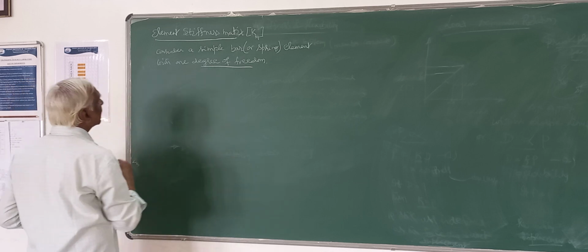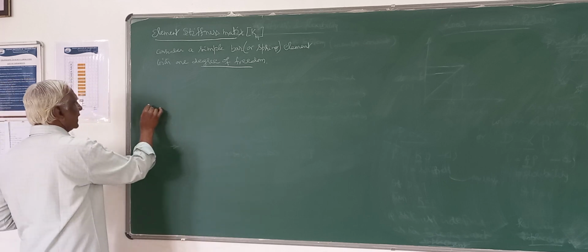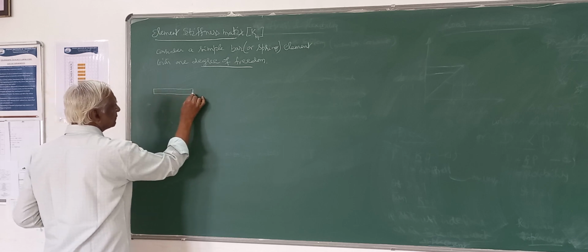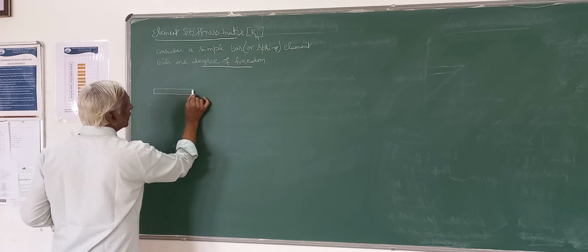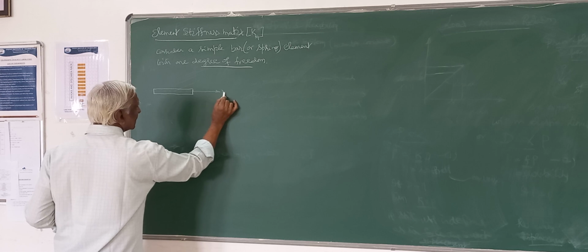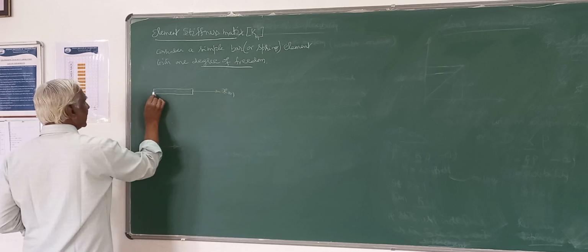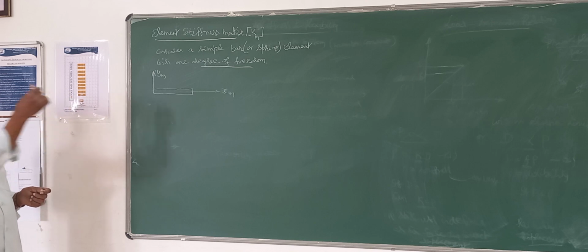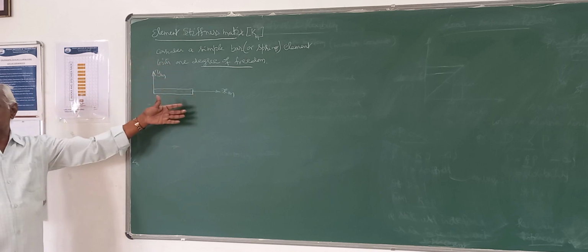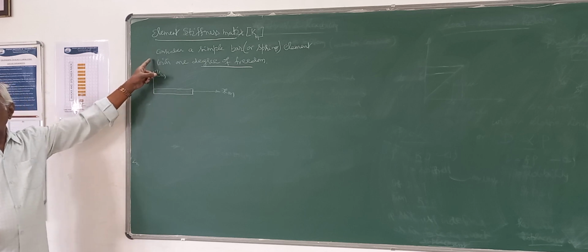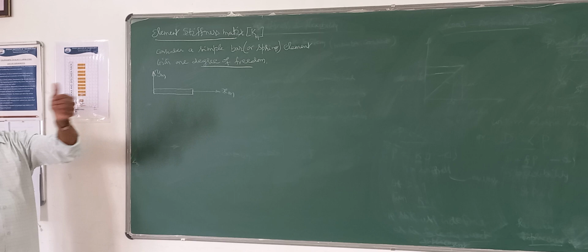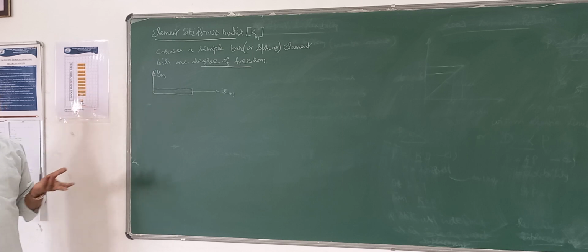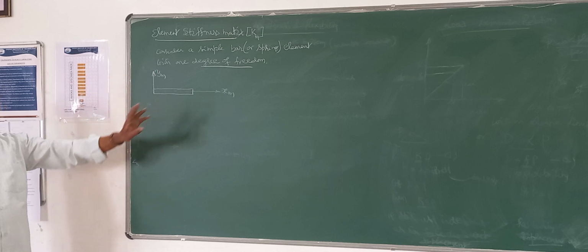So consider a bar element with 1 degree of freedom. A bar is a simple line element, so your local coordinate system will be like this. This is the local or member x-axis and this is the local member y-axis, and of course the z-axis will be normal to the plane, because we are dealing with planar structures. These two are planar orthogonal axes. The other orthogonal axis will be normal to the plane, either outside or inside the plane of the board. That is your other local axis.